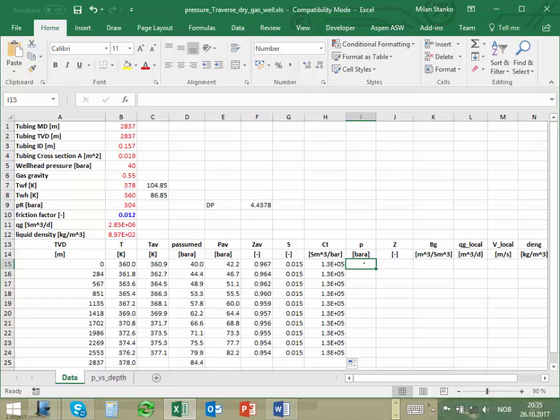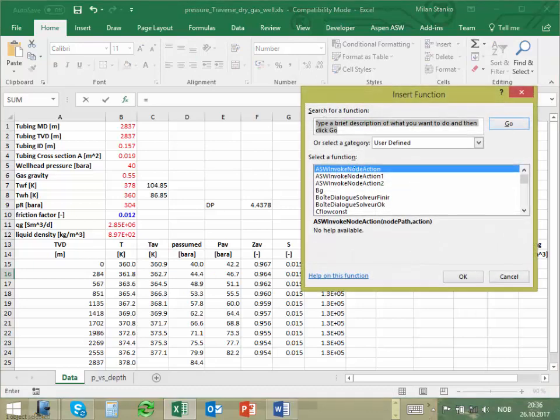Okay. Now we start calculating the pressure. What is the first pressure? Separator pressure, okay, 40. Then to calculate the next, which equation do I use? Tubing, okay, the tubing equation. But we have three of tubing: Q, tubing P1, and tubing P2. Which one do we use? Okay, we want the pressure at the inlet of that section. So we say tubing P1